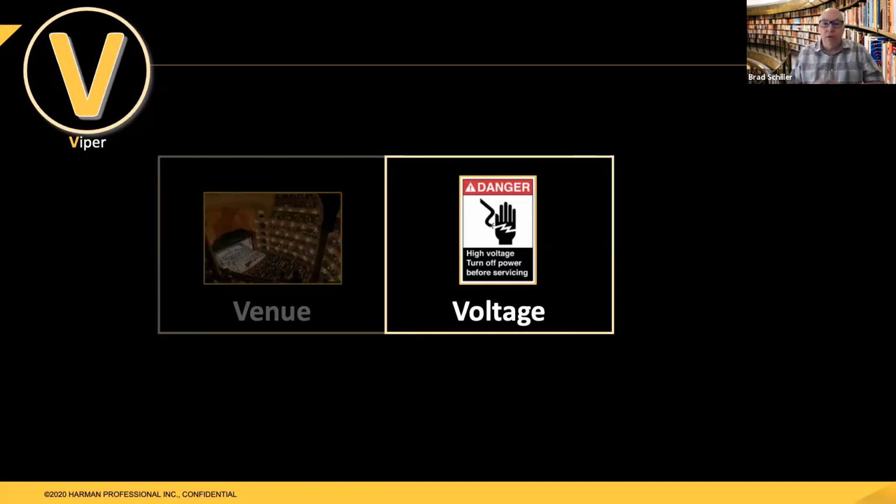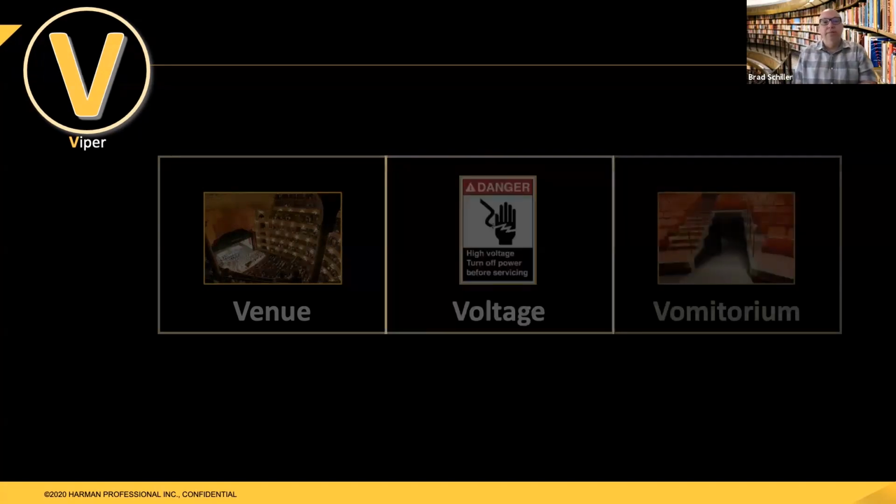And if you get the voltage wrong, if you have something that's made for 100 volts or 120 volts, and you give it 240 volts, you're going to blow it up. Or vice versa, if you have something that goes the other way, it's not going to operate. So it's important to know the voltage of your products.